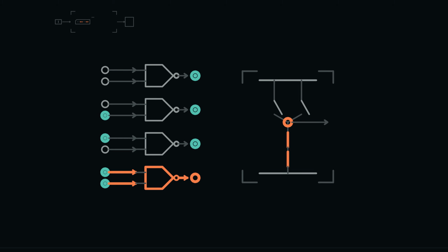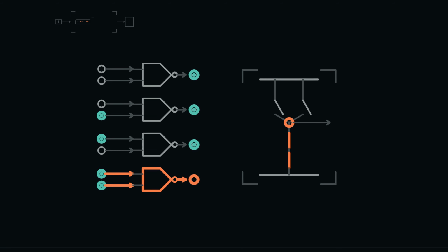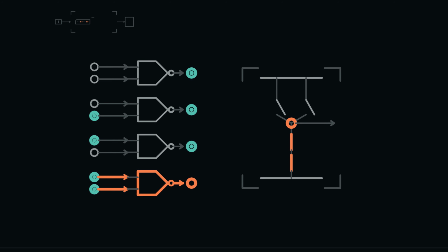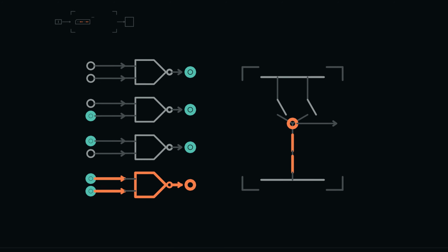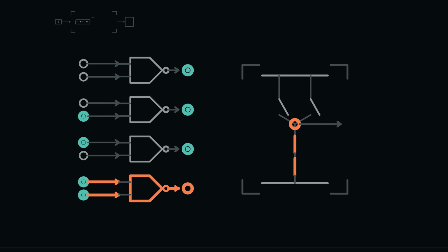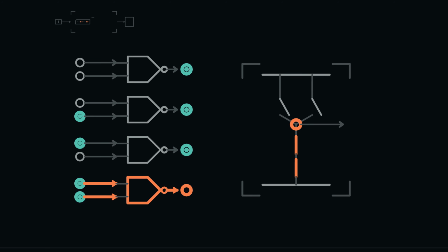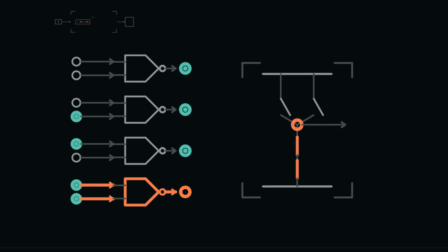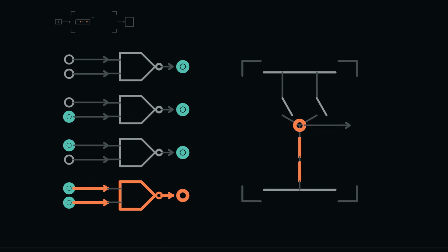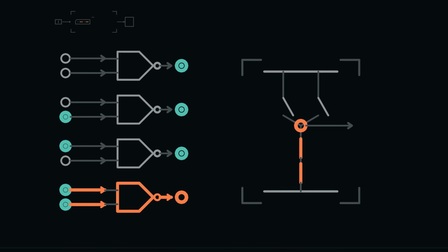Why are those relations enough? For every truth table row whose desired output is 1, AND conditions matching that row, using NOT where it requires 0. Each term recognizes one row. OR those terms together and the result is 1 on exactly the chosen rows. If no row is chosen, A and not A supplies constant 0. Since NAND constructs NOT and OR, it can construct any finite Boolean truth table relation.